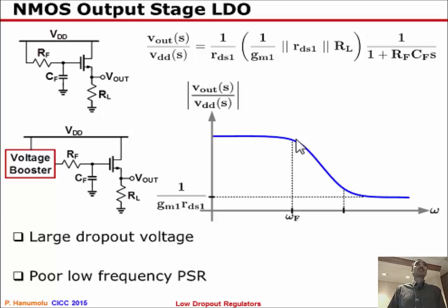But if this oscillator is going to be embedded in, for example, a PLL feedback, the PLL itself is going to provide some low frequency rejection. So in which case, you don't really need to do even more stuff of regulating or suppressing low frequency. The other loops that you are going to use this LDO with may suppress some of this, and all you care about is this. In those applications, this can be quite useful.